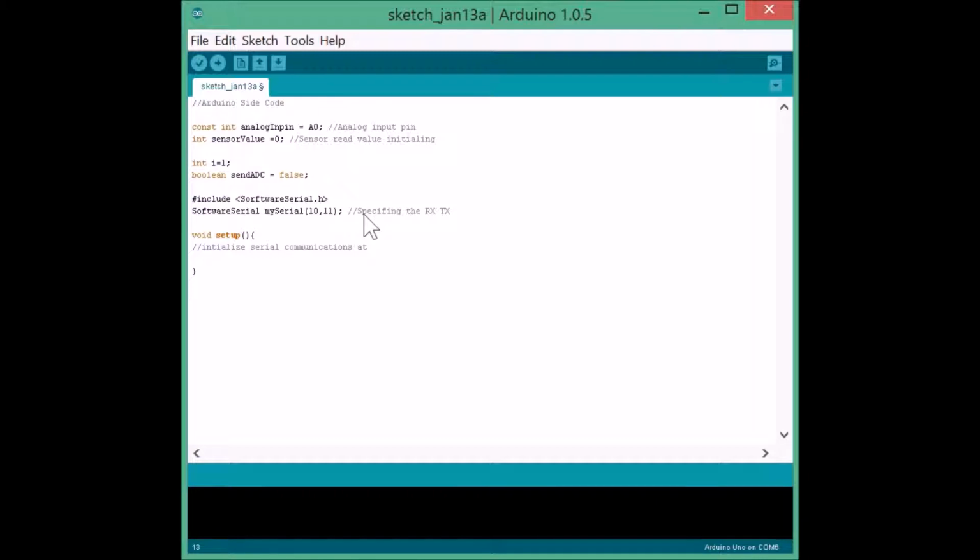We'll be initializing this at a baud rate of 9600. There's no specific reason why I'm using this baud rate, but it is the most generic one you will find. So I'm just initializing the serial. As I already told you, I am using a library implementation, SoftwareSerial, to keep things easier while we are programming again and again. We'll now need to set up the object which I initialized as my serial. We'll also need to initialize that.